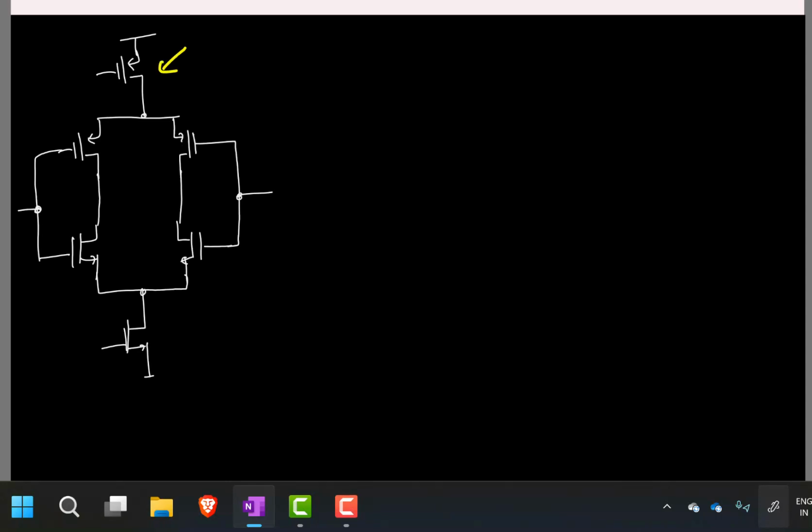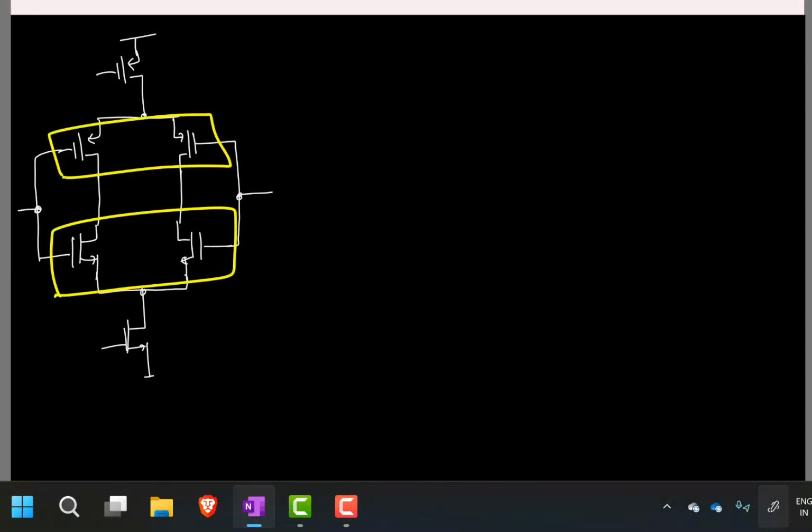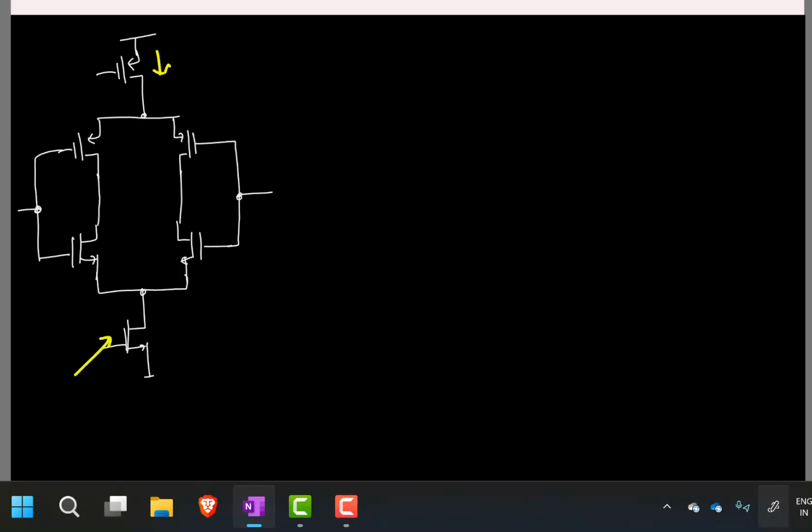We need this current source because, what is the reason for having a current source in a diff amp? We need common mode rejection. So this one has common mode rejection, and similarly even this gm needs common mode rejection. And again, you need common mode feedback here. You can assume this current is fine and tune the other current source, or vice versa. The same thing you can do for the output stage also.